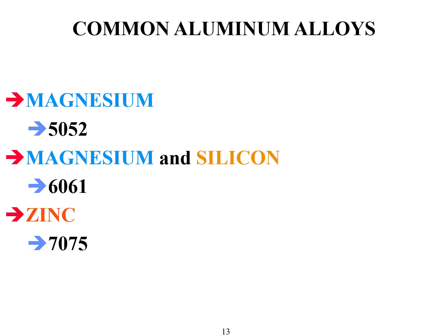You can use the typical aviation alloys. Magnesium base is 5000 series, 5052 is common. If they add some silicon to it, that's your 6061 materials that's used in aviation and throughout many industrial applications of aluminum. Then finally, our hardest, toughest, meanest would be a 7075 material where zinc is your primary alloying ingredient. I've always found it ironic that some of the things that we need to keep us healthy are also included in these alloys of aluminum.